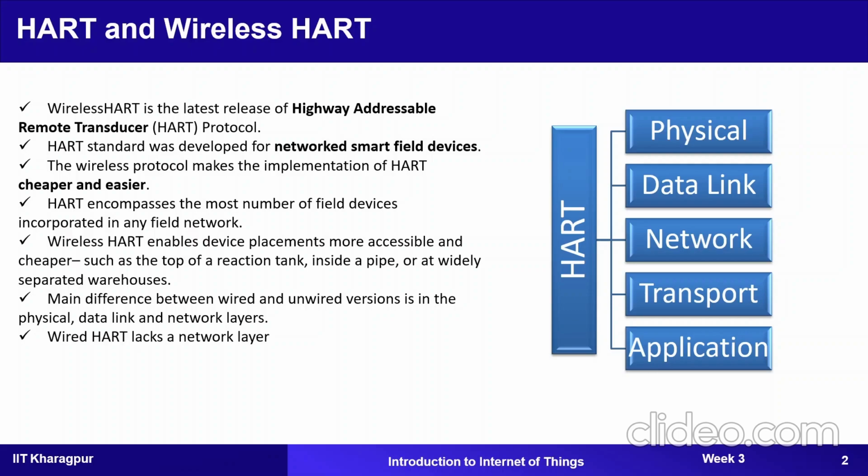So basically, whenever there is some change in the network, this network manager is going to update the information to each of the nodes. It also decides who will send the data, who will listen to the information, and what will be the frequency of each time slot. It handles the code-based network security and prevents unauthorized nodes from joining the network.